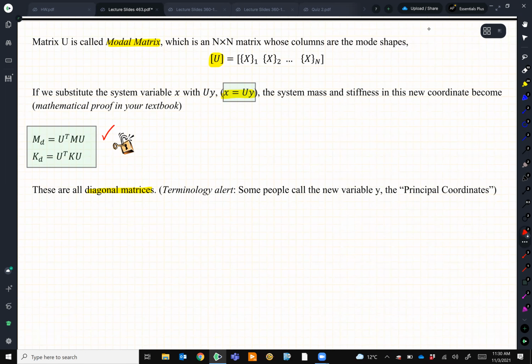But for somebody who analyzes vibration, the eigenvalues are the natural frequencies and the eigenvectors are the mode shapes. And that's the beauty of math. Here we have a purely mechanical system, and we solve the equations. At the end, we found that the eigenvalues of this system are the natural frequencies.